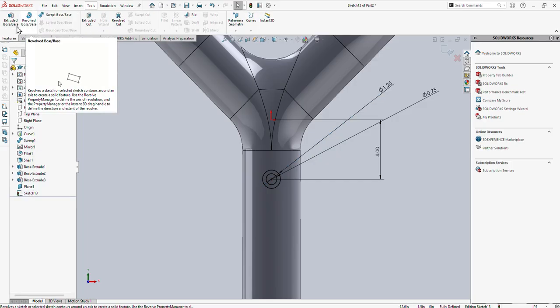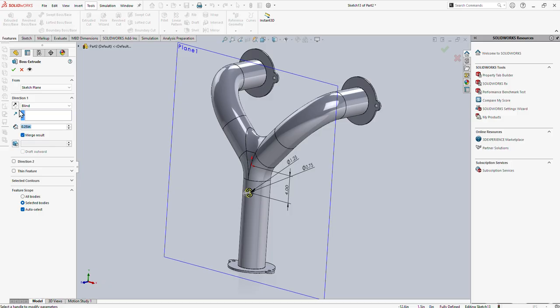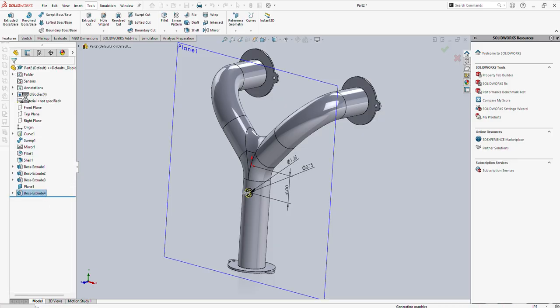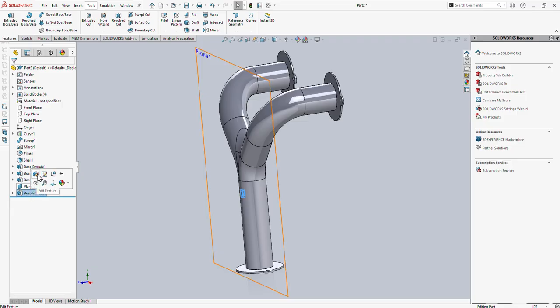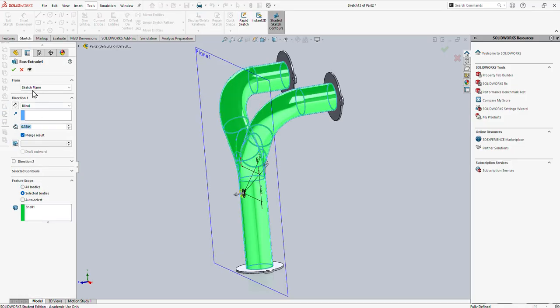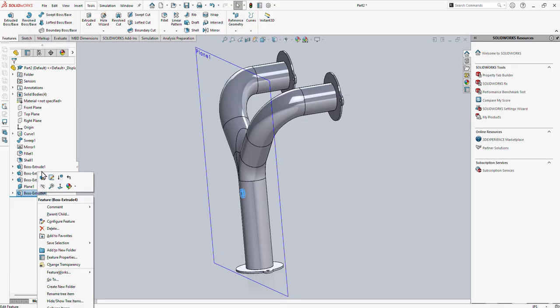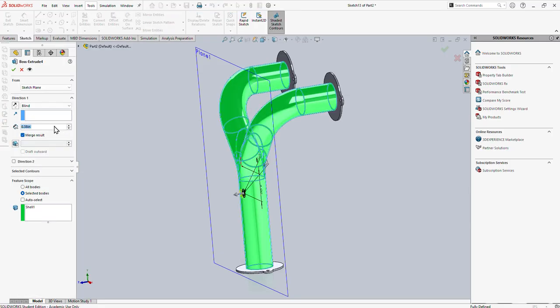So let's do this, extrude, and let's go outer edge, and I want it at least 3/8 of an inch. Okay, oh no, I have to go more because I have this 1.5, so I have to do it actually more. My bad. Let's modify this and let's go add plus 1.5. That's actually too big, so let's do 1 inch. Now this is good.